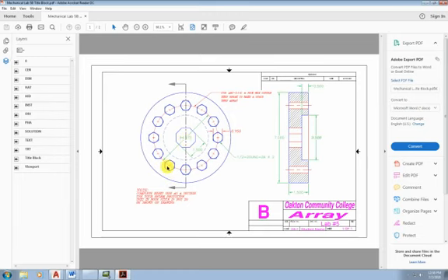This is almost complete. We've got the outside diameter, we've got the bolt hole circle center line. We need this hidden line, which represents this part right here. If we were to look at this, this is a section drawing, meaning that this is a representation, the right side, if I cut this in half with a saw along this section line. And so what it shows, it doesn't show the bolt heads, it shows the holes that the bolts go in. And then it shows that this polygon shape here is actually a hole that goes through it, and then beneath it there's a round relief area.